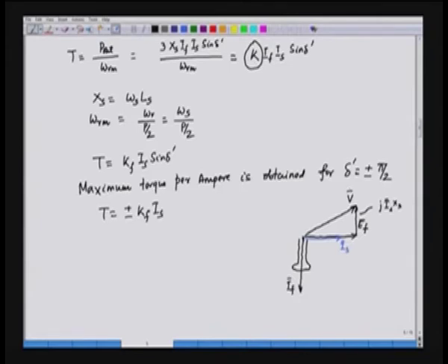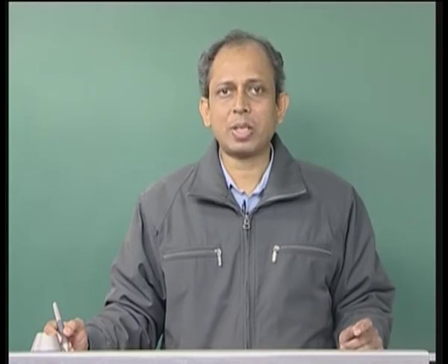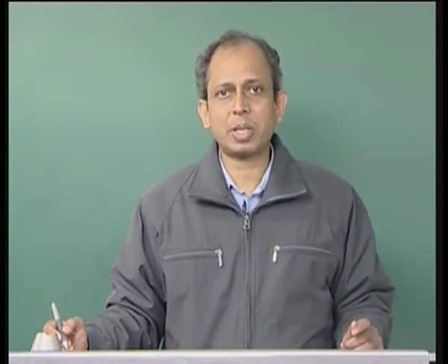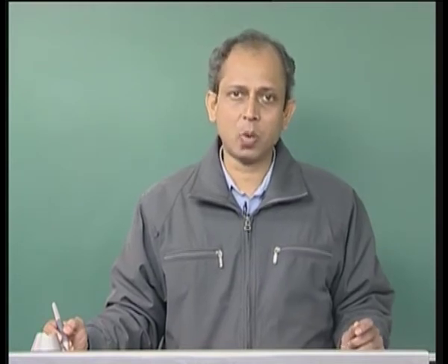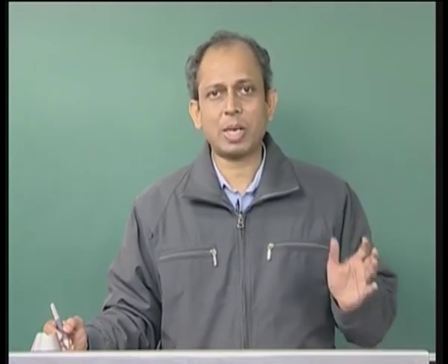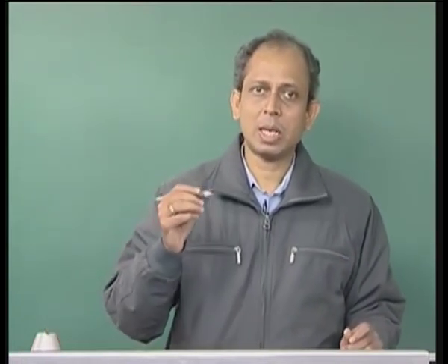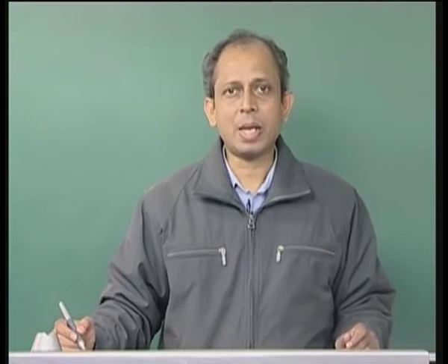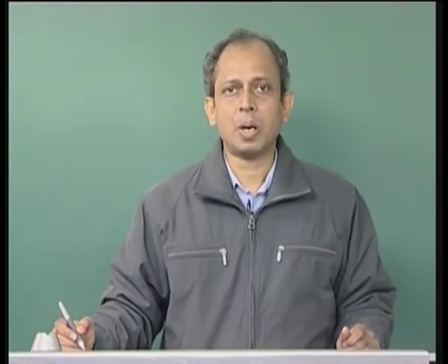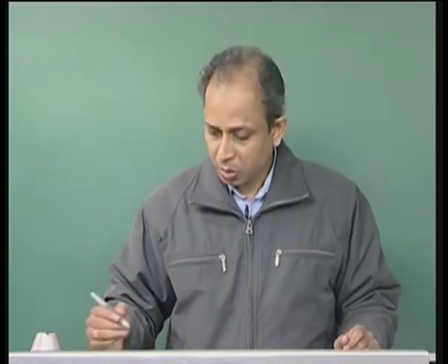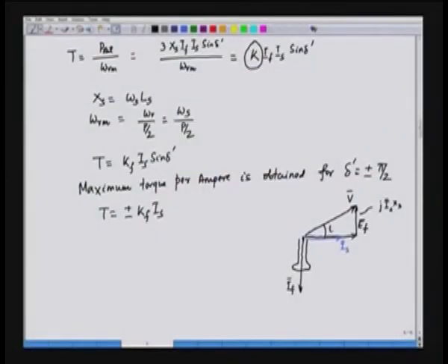So, this is the condition for maximum torque per ampere, and this is in the motoring region. Now, we see in this case the internal power factor is unity. EF is in phase with IS, and hence the internal power factor of the motor is unity. However, the external power factor, which is the angle between the voltage and the current, V and IS, is non-zero, and in fact we have a lagging power factor here. This is the external power factor angle, theta, and IS is lagging behind V. Although we have an internal unity power factor, the external power factor is lagging.